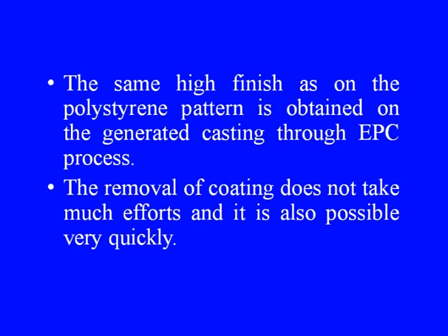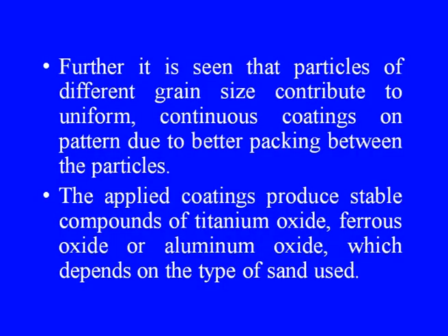The same high finish as on the polystyrene pattern is obtained on the generated casting through evaporative pattern casting. The removal of coating does not take much effort, and it is also possible very quickly. Further, it is seen that particles of different grain size contribute to uniform continuous coatings on the pattern due to better packing between the particles.